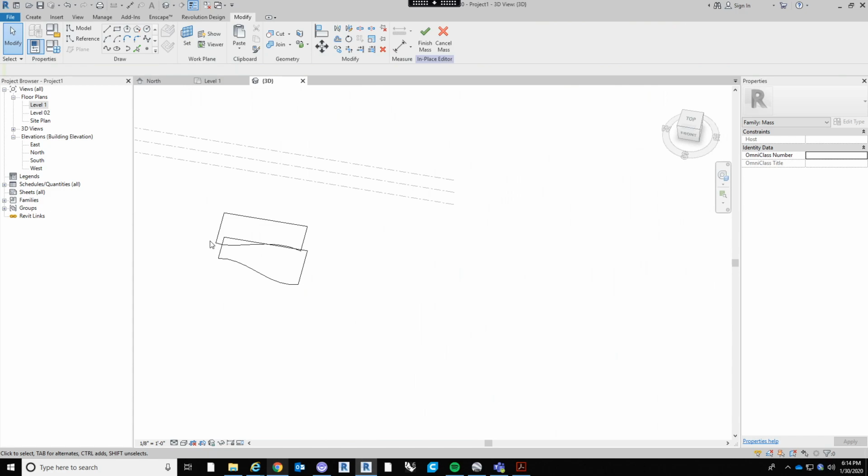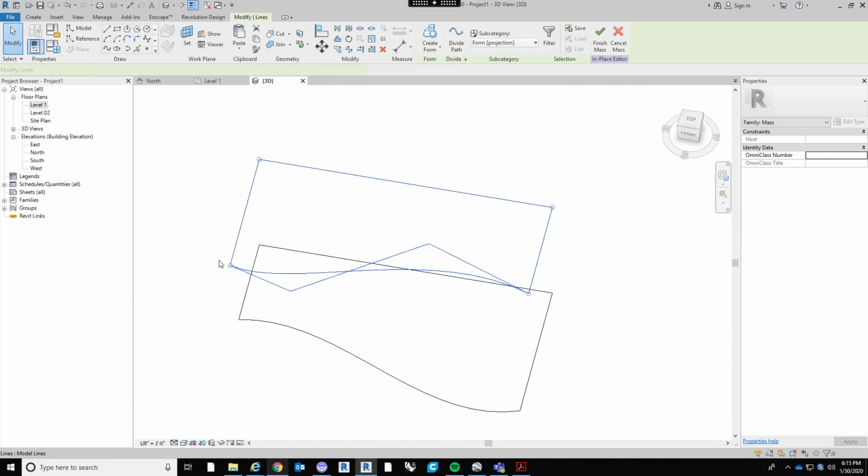Can these lines, do they snap at all, or do you just have to kind of know where you're placing it? So that is one of the issues: if you copy or mirror or offset the splines, they lose all adjustability, and that includes snapping too. So typically the original ones are decent, like they actually have control points that you can snap to, but if you do anything to them, they lose that. That's one of the big drawbacks of the spline tool.